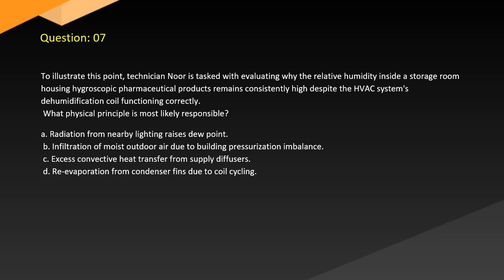Question 7. A technician is tasked with evaluating why the relative humidity inside the storage room housing hygroscopic pharmaceutical products remains consistently high despite the HVAC system's dehumidification coil functioning correctly. Which physical principle is most likely responsible? A. Radiation from nearby lighting raises dew point. B. Infiltration of moist outdoor air due to building pressurization imbalance. C. Excess convective heat transfer from supply diffusers. D. Re-evaporation from condenser fins due to coil cycling.